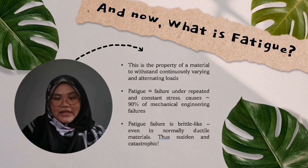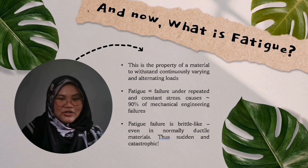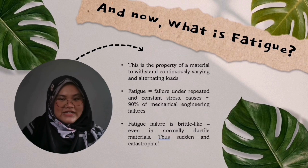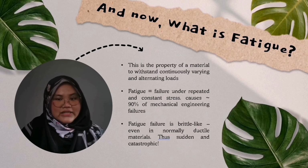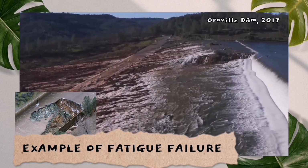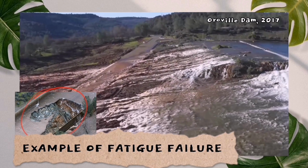To make it simple, fatigue is the property of a material to withstand continually varying and alternating loads. Fatigue equals failure under repeated and constant stress. It causes 90% of mechanical engineering failures. Fatigue failure is brittle-like even in normally ductile materials, thus it's sudden and catastrophic. An example of fatigue failure is what happened at Oroville Dam, California in 2017. The problem started when a giant hole suddenly opened up in the chute.